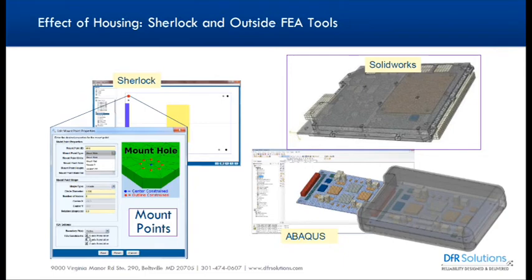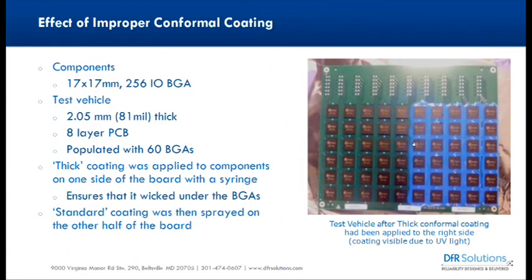There it is. So you see right here, if you undo the X and Y constraints in the FEA constraints for any one specific mount point, you can actually virtually do the effect of the case. Not only that, in Sherlock 6.02, you can actually determine the case material. When you do the X, Y, and Z constraint, Sherlock will say, I don't actually model an aluminum plate, but I'm going to force the mount point to move as if they have an aluminum plate attached to them. So yes, the answer is absolutely yes.